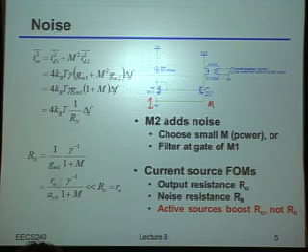So if you remember that the ratio of the gm between these devices, gm2, is just going to be 1 over m times smaller than gm1, right? Then you can pull out the gm1 to the front here, and you see that there's this 1 plus m factor in front of what I would have expected to get from my noise current, okay? In particular, if I had a 1 to 10 mirror ratio, that would mean my noise current is 10 times larger than I would have thought. In fact, actually 11 times larger than I would have thought, just due to the noise current of this one device here. Okay?